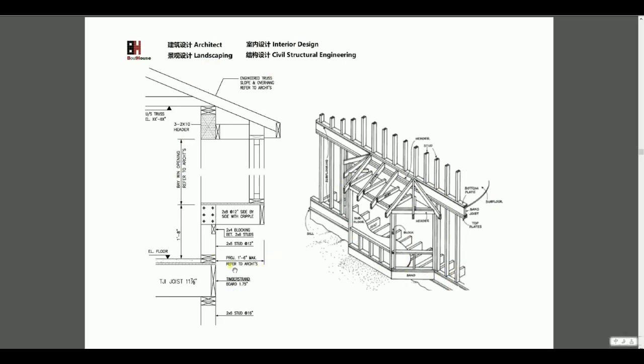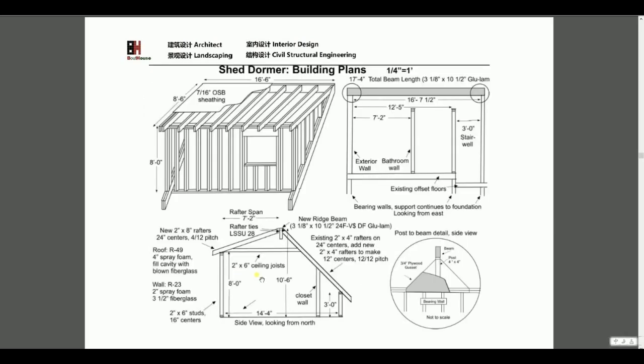For the bay window structure design, we focus on the projection here. The projection is limited. Eighteen inches is the usual projection for the building code, but if we have more projection, we need to put some brace here. We usually see some photos in the street with bracing here that looks like this shape.